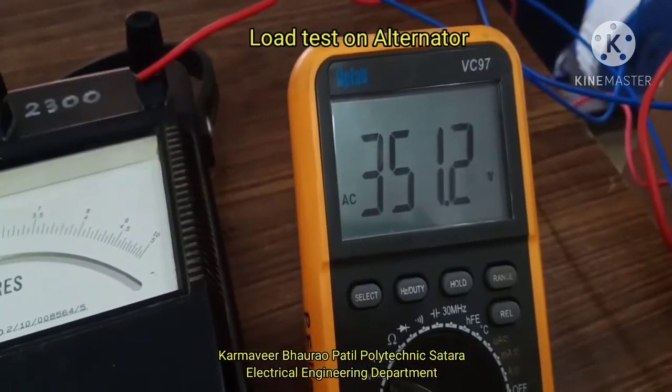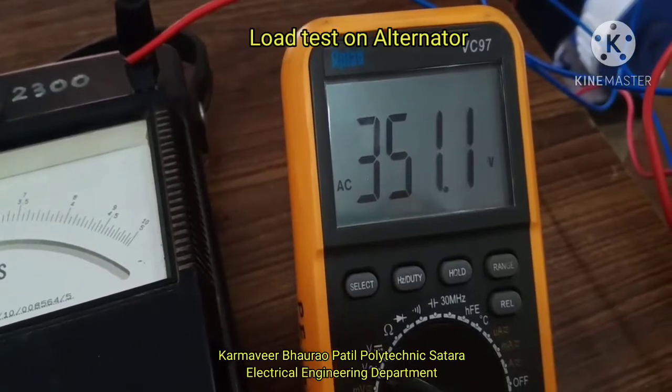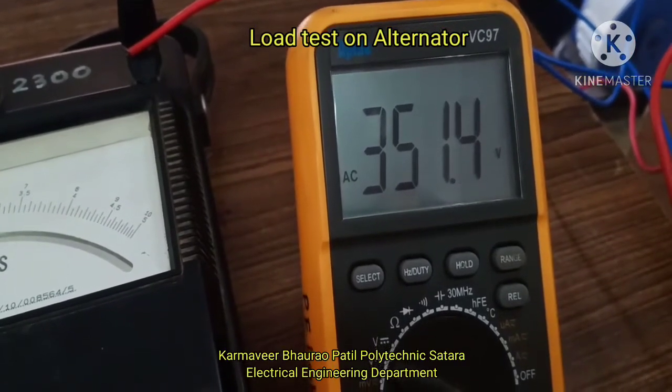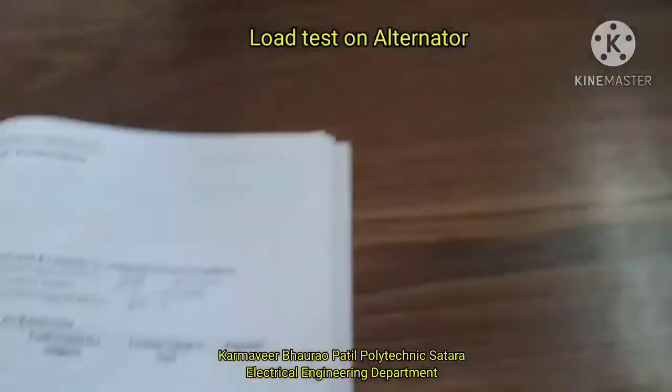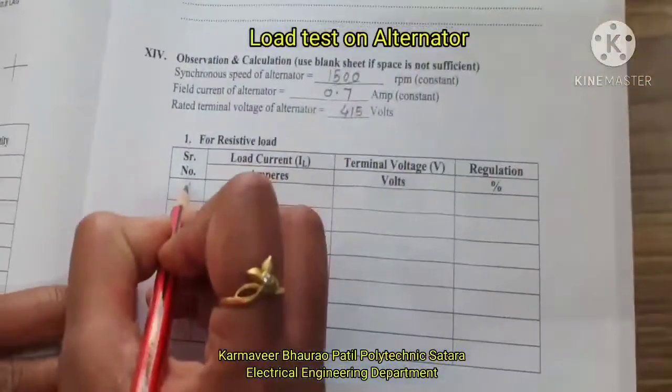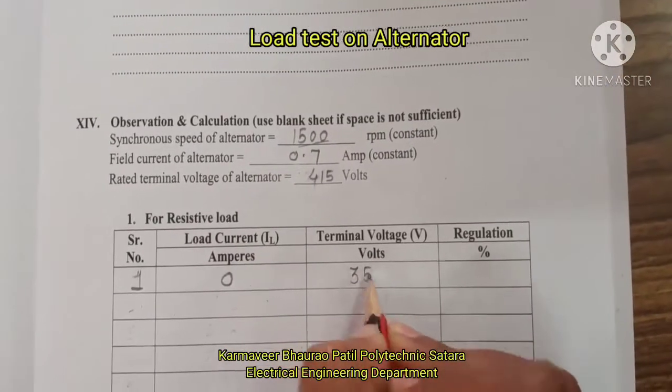By increasing the excitation of the rheostat, we have adjusted the alternator output to 351. This is our first reading with no load, so we'll note down the reading. For resistive load, IL equals 0 and voltage is 351.